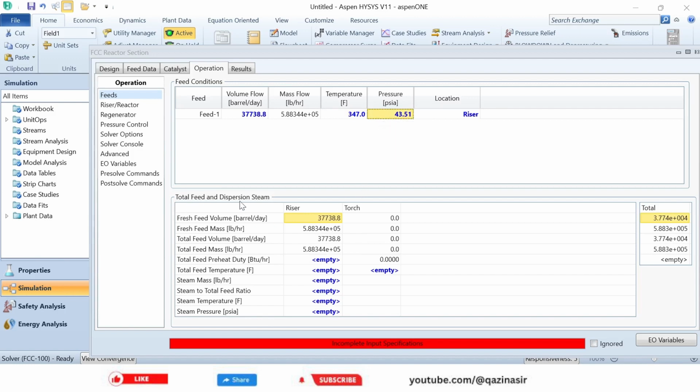If you move to the total feed and dispersion steam information, the preheat duty in BTU per hour is 0. We have the steam mass flow rate in pounds per hour, which is 1.012 times 10 to the 4. We have the steam temperature, that is 392. We have the pressure of the steam, which is 145 pounds per square inch absolute.